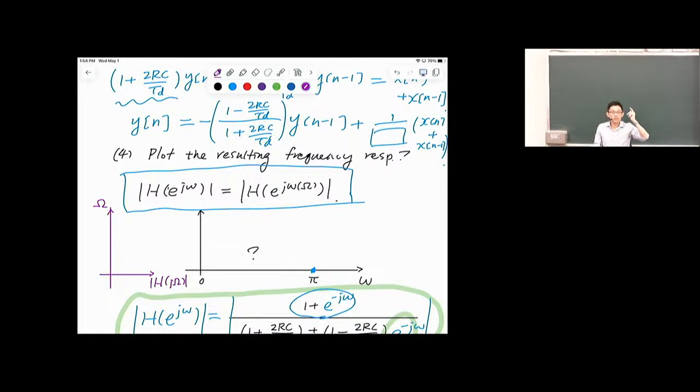For the Butterworth filter, we have a corner frequency big omega c in your prototype, and the response drops from 1 to 1 divided by square root of 2 right here, and then it's monotonically decreasing but never touches 0. That's how a low-pass Butterworth filter looks in the big omega domain.